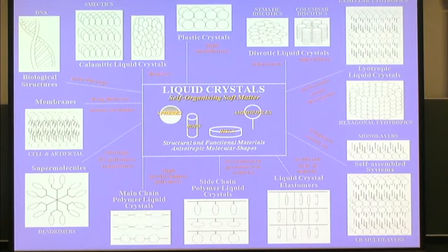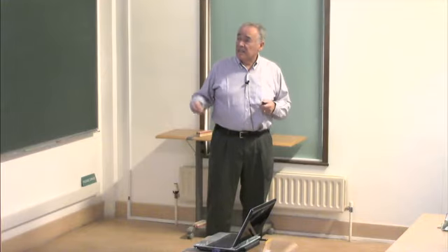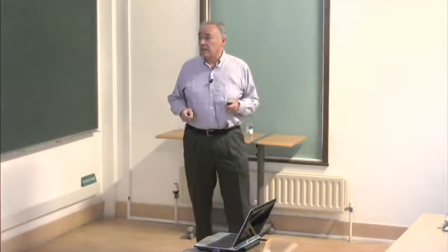Down here, we show liquid crystal polymers. You can incorporate these rods or disks on polymer main chains. So these are high-performance fiber materials. You can incorporate them as a side chain, used for ferroelectric, piezoelectric sensors and other display applications. And here we have liquid crystal elastomers, so we cross-link the polymer chains. So these are materials that are being developed for artificial skin and muscle.